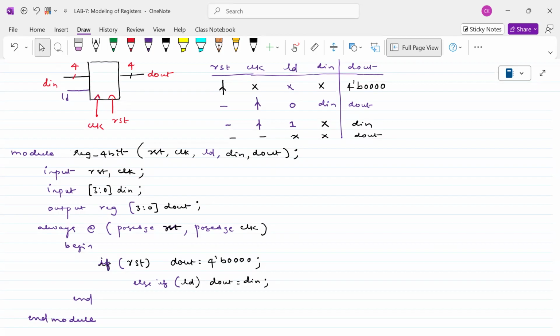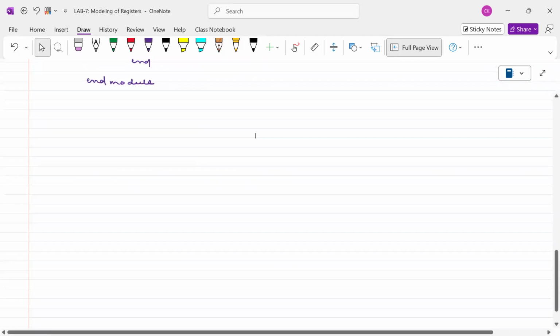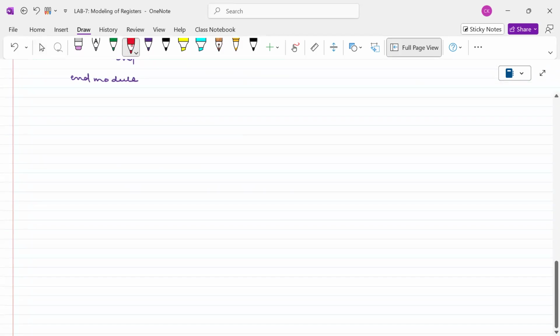You may ask why you have written the code like this. Already I have written the D flip-flop code previously. Why can't I use that D flip-flop and create a structural model? So let us see how to design the 4-bit register, and from that, how to write a Verilog program for it. Because I'm going to make use of the previous 1-bit D flip-flop, which we have already written. Let me write a 4-bit register using structural modeling.